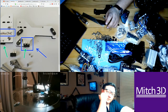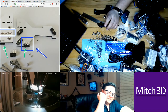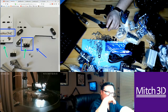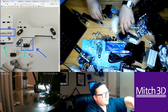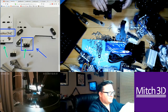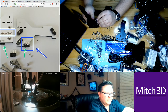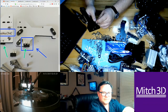The arm length affects the scale of the part, the print in XYZ. The delta radius affects the curvature of the print, I think. And then your tower offsets and all those things affect your XY, actually all the scaling. As far as I know. But again, I've been working with delta printers for a couple of years now, and I still don't quite understand how they work. It's just math.